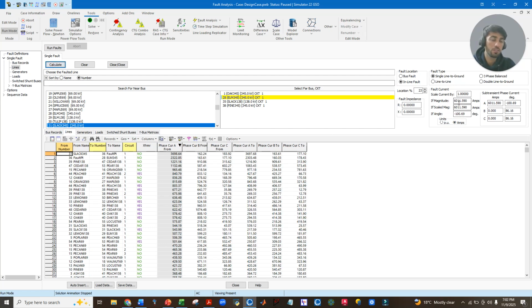So it will be a 6000 ampere short circuit current, and if we want to scale it up to 25% and calculate again, the actual value will be almost 6000 ampere, and the scaled value will be 7.5 kiloampere. So this is the way we can conduct short circuit analysis at a transmission line to find the short circuit current values for the safe installment of circuit breakers.